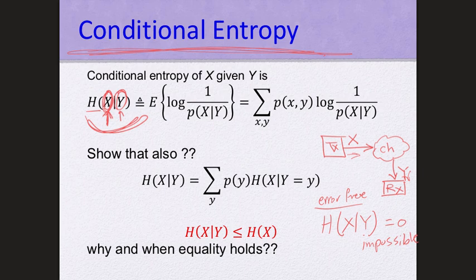And electronics at any temperature higher than absolute zero, minus 273, right? Any temperature higher than that will cause the electrons in the receiver components, which are resistors and transistors and so on, to move randomly, which is going to disturb a little bit your voltages coming out of the electronics, and this is what we call noise.